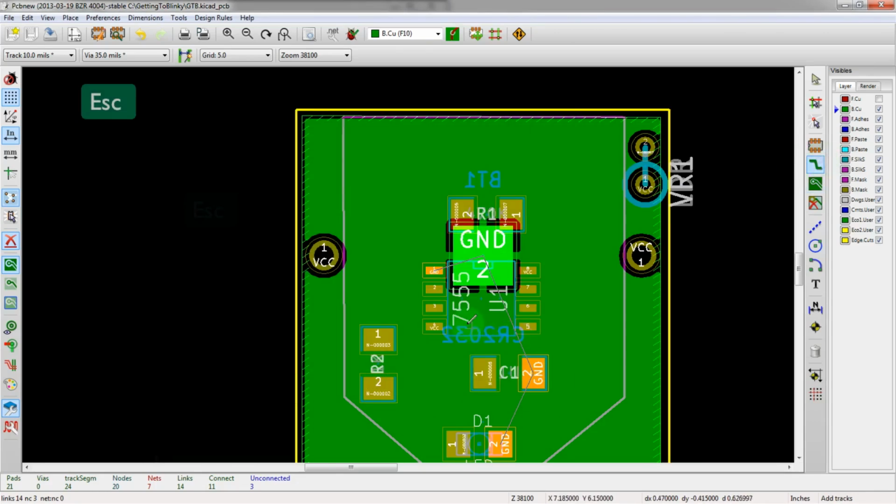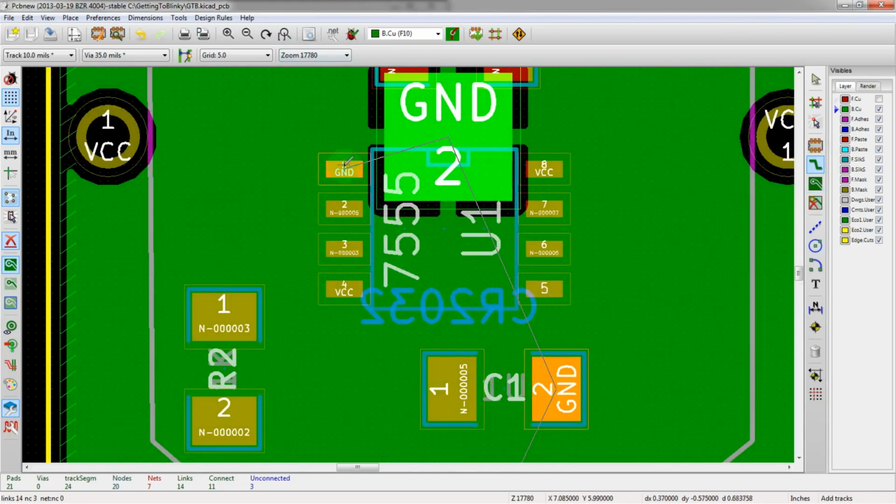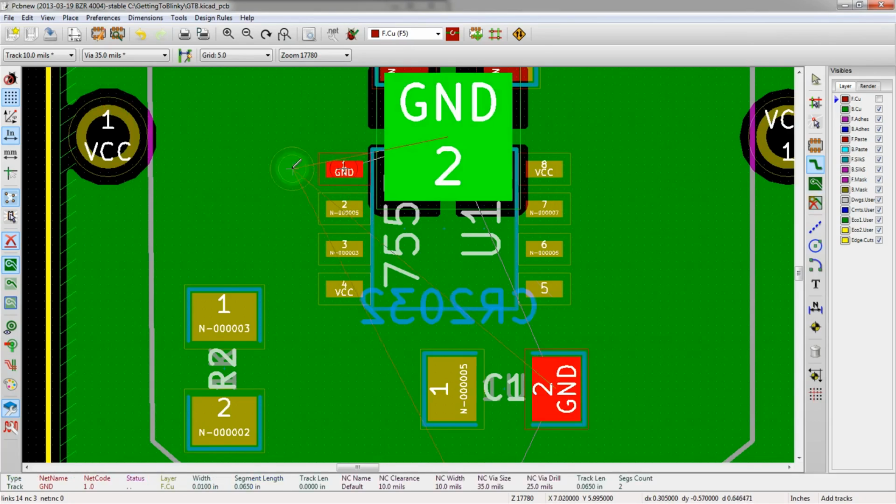All right, now the final thing we need to do is to actually connect up, oops, wrong thing. Go back to the drawing vias. So we want to hit V, so we go to the top layer copper. We need to connect the top side pad here, pin 1, to somewhere in the ground plane. Now we don't actually need to connect it to here, even though it's close, we could. Instead, what we can do is we can just draw a trace. Oh, that's terrible to look at.